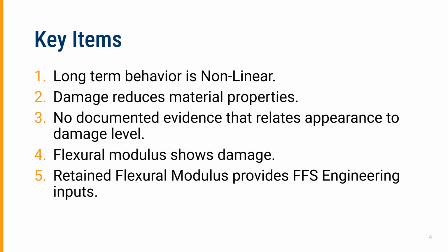Third, there's no documented evidence that relates the appearance of FRP to the damage level that it has experienced. Fourth, the flexural modulus actually is used to show the extent of damage. And fifth, the retained flexural modulus provides fitness for service engineering inputs.